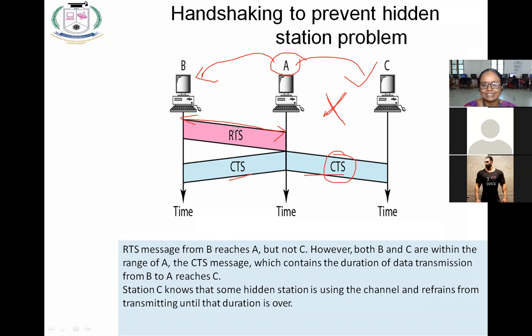So that is the purpose of RTS and CTS. It's like a handshaking signal. In a microprocessor, you have studied HOLD and HLDA. First, it will ask the request whether I can communicate with the processor. If my microprocessor acknowledges, automatically my peripheral will communicate.